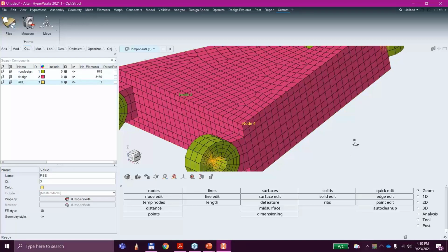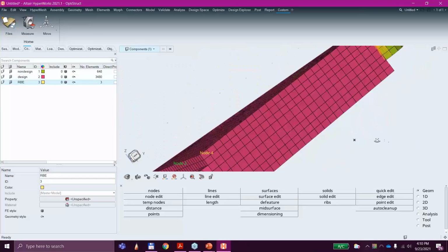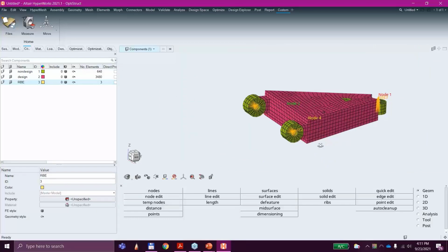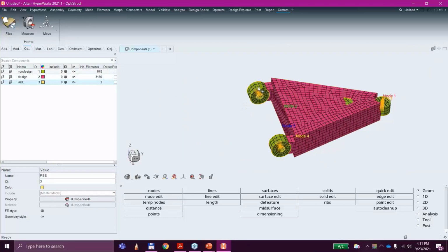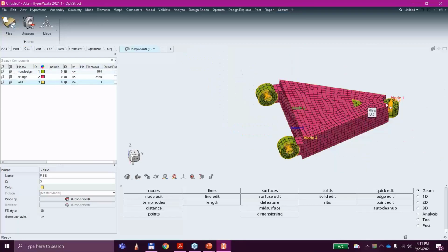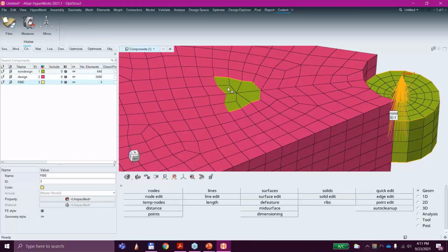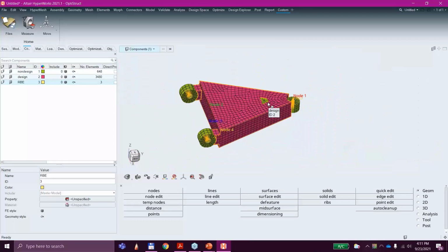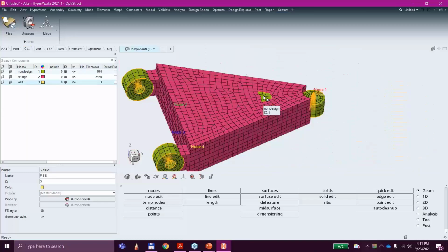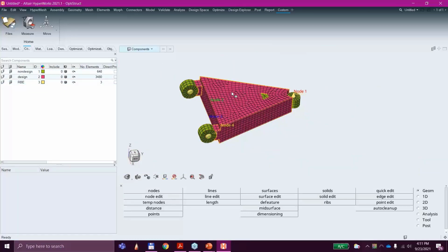So this big pinkish looking chunk here, that is all going to be my design space. These mounts here are non-designed because this is where it attaches to the vehicle and the wheel here. And then they put this little guy in here because of the jounce bumper. So that's where it has to have a positive stop right there. So anything in pink can be gotten rid of.